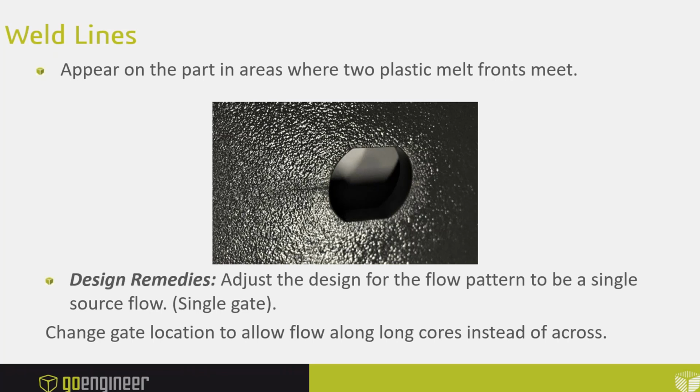Weld lines also appear when there's some sort of flow around a hole. So this is like a through hole, and you can imagine if my face represents where that hole might be, right? Or think about just water moving around a rock, right? It hits the rock, diverts left and right, and then comes back behind it and meets.